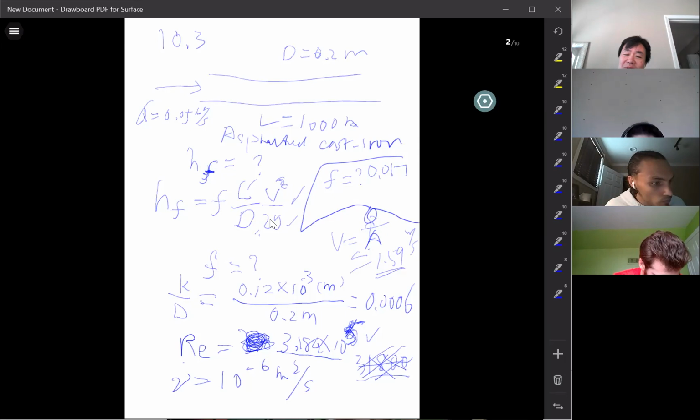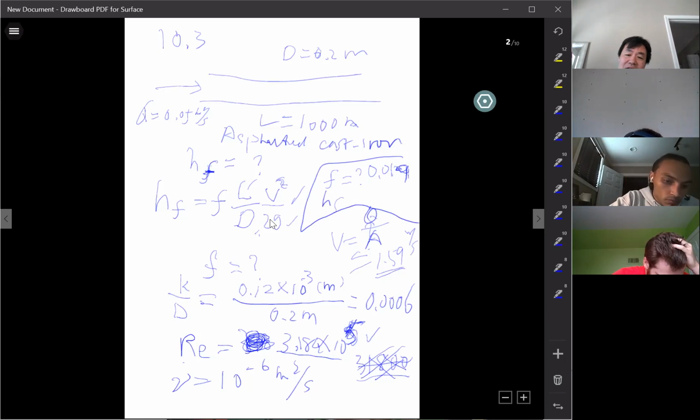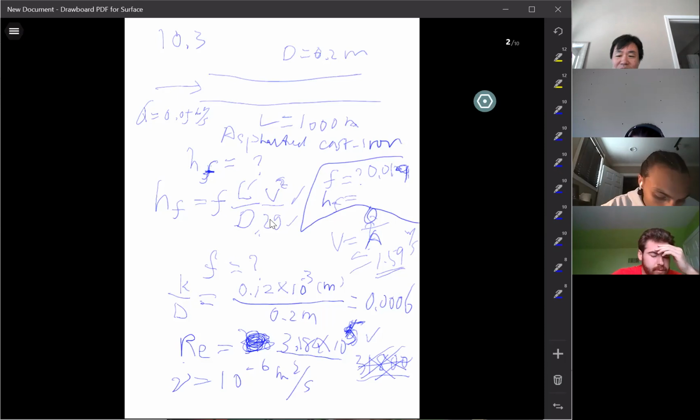See, reading those tables is not that easy, because the Reynolds number is not in the hundreds or thousands. It's kind of in between. So you have to interpolate a little bit, get a straight ruler or something like that. I think in the textbook it says 0.019, but 0.018 should be close enough. Okay, based on the 0.019, can you calculate the frictional head loss for me? Give me a final value.